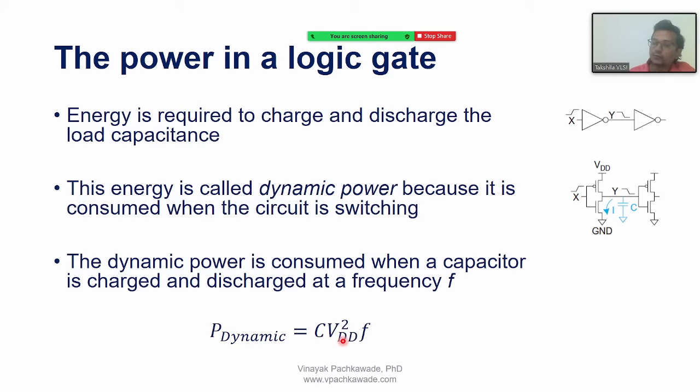Second, the square of VDD. The most important thing we see is that the higher the supply voltage, the higher the power consumption, and that's why in modern technology today, when the scaling of the transistor is happening, or when we are talking about nanometer technology nodes, supply voltage scaling is also happening, because for a 1 nanometer transistor you cannot operate that transistor with 5 volts.